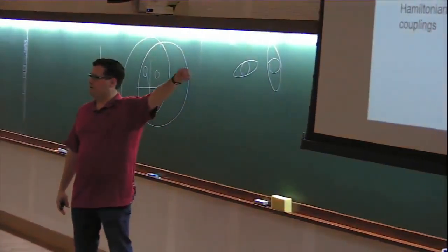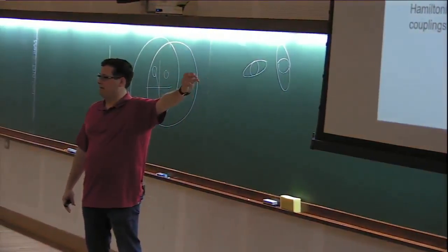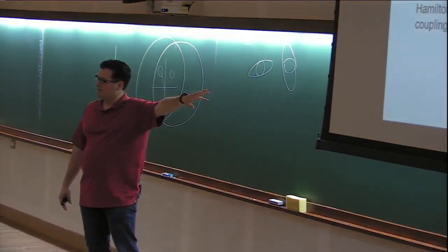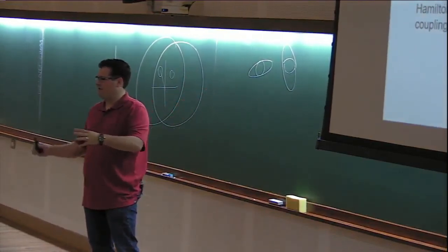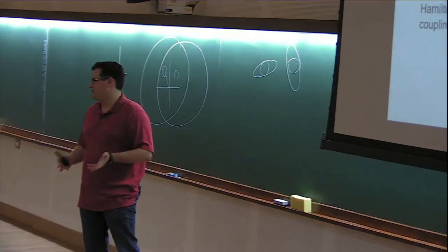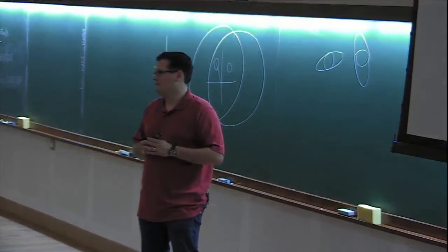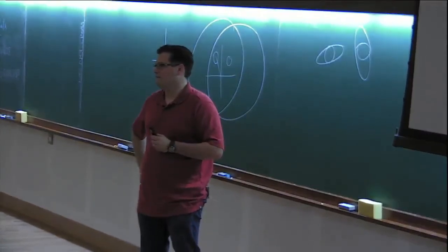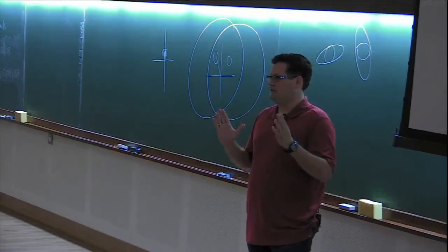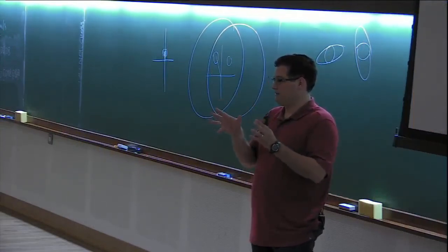So in many of the 4-8 qubit experiments, they just brute force it. But no one has a well-conceived notion of what 10,000 qubits will look like, so I can't tell you where the economics will land. One amplifier can work for many qubits. We would like it so that, for instance, you could spread the qubits out in frequency space, and if the amplifier was broadband enough, it would just amplify them all.